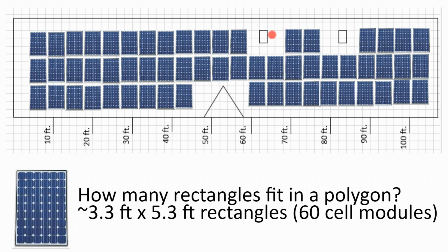What began to leak is the stuff that's already on the roof, that's already 10 to 15 years old. Wherever there are no panels on the rooftop, like the clearance left around the skylight, that clearance becomes a walkway during construction. So you have workers tromping up and down around this skylight, and then the skylight begins to leak. That shouldn't be a surprise to anyone.